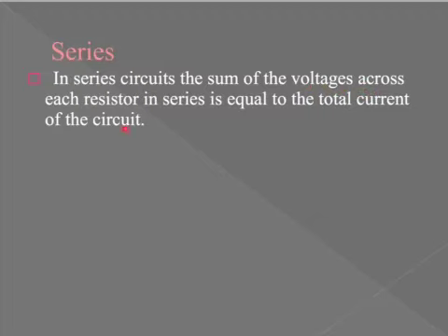So how do we find that? Well, we need to use our equivalent resistance circuit, because that allows us to find the current through each one. Once we find the current, we can go ahead and use Ohm's law again to find the voltage in each of these cases. So we're just going to do that right now. First we're going to use this one.